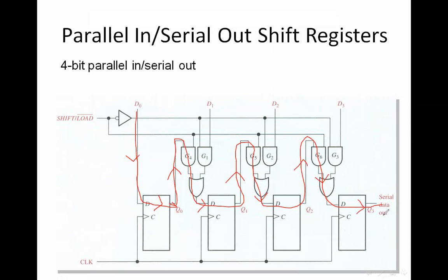Right. So this is the way your data passes through from one flip-flop to another flip-flop. So this was in parallel in serial out. Now when I go with parallel out, okay, which means this serial connection has to be removed, right? The serial connection has to be removed. So in order to do that, I have to cut short all of these connections, which means there should not be connections from one flip-flop to another flip-flop, right?